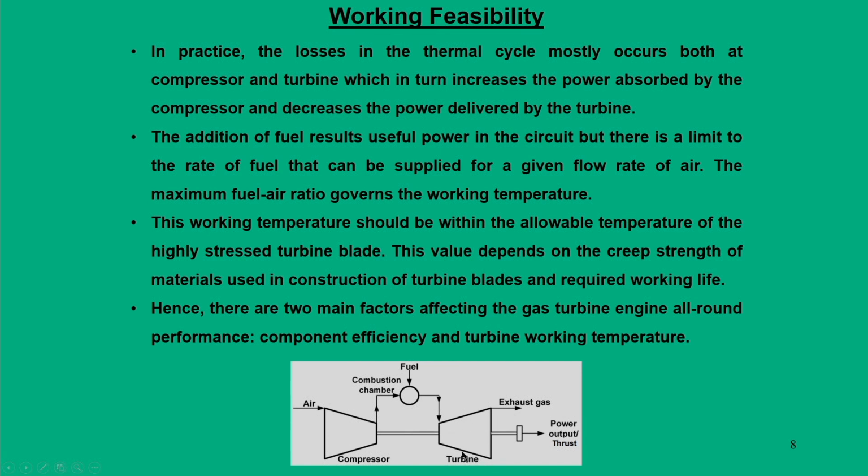In fact, at different locations of the turbine we will have very high temperatures, and since it is a continuous operation, high temperature material requirement becomes a necessity, because the thermal endurance that the material is going to sustain over continuous operation, as well as the thermal fatigue, becomes an important concern. And typically this temperature could be as high as about 1500 degrees Kelvin. And that is a continuous 24-hour operation, and continuous operation gives thermal fatigue.